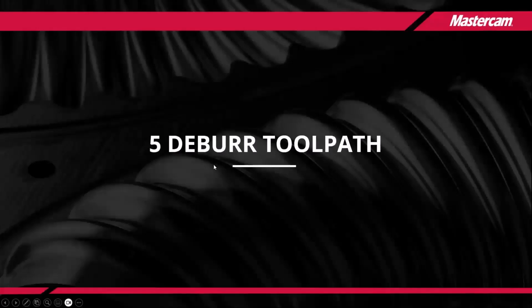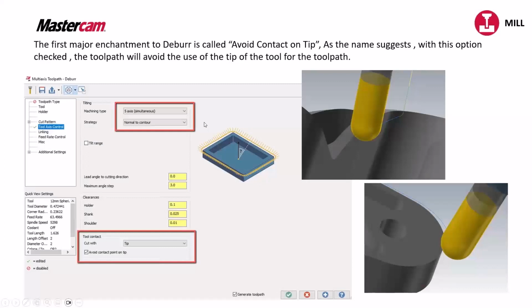So for the deburr toolpath now, they've added a few changes. One of the major enhancements that they put in is called avoid contact on tip. In one of the previous deburr toolpaths, if you're using 5-axis normal to contour, you're going to get the ball of the tool right on the tip.